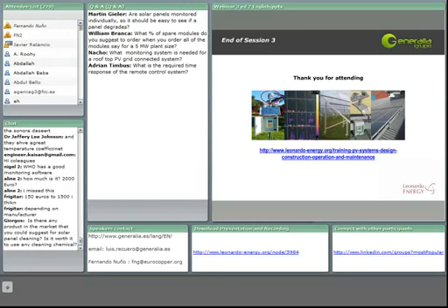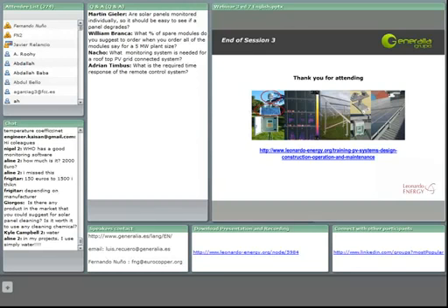For example, if we have detected that the position of a sun tracker is not synchronized with the position of the sun, because we are detecting that the energy produced in that sun tracker is lower than the energy being produced in the rest of the sun trackers in the PV facility, it is important to be able to modify in real time the data for that sun tracker and modify the position.